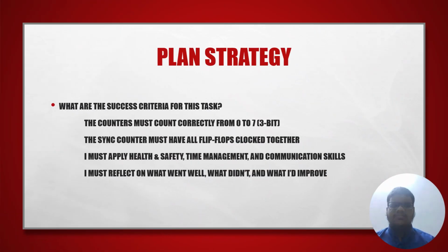Success criteria. The success criteria were that both counters must count correctly and reliably. For the asynchronous counter, the clock signal was a little bit of a ripple. It was rippling through each flip-flop, which naturally introduces a delay.